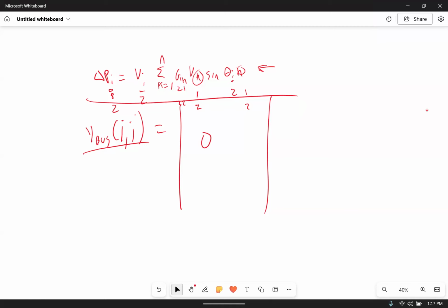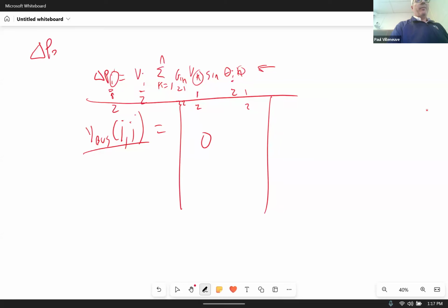Okay, so if VI represents V2, then, because obviously PI is defined right here, right? That's where we define it. So it's delta PI. If I'm writing a power balance equation for delta P2, then I know for certain that I is going to be equal to 2. Okay, so then that's where, if you have your 3-bus system, you have a slack bus, so you have like P2 and P3, then I will obviously just correlate with what you're searching for. Correct. Okay, okay. All right, thank you.